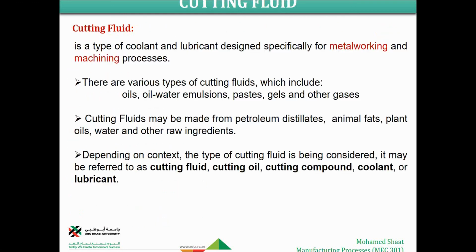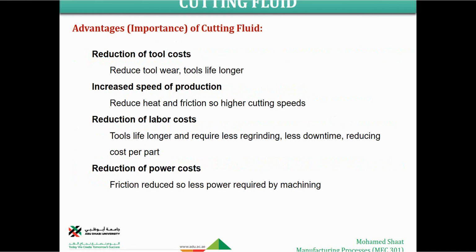So that's why we also discussed the cutting fluid. We said that this cutting fluid is important to get rid of the heat generated, and we discussed the two sources of the heat generation. One is due to the breakage of the chip, and the second one is due to the friction between the chip and the top rake face of the tool, or the workpiece and the flank face of the tool itself, right?